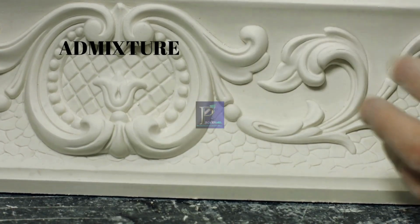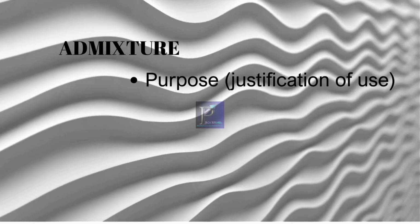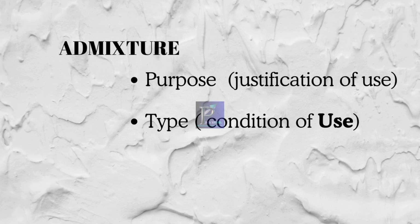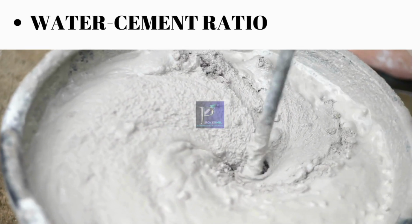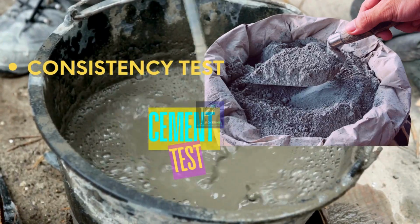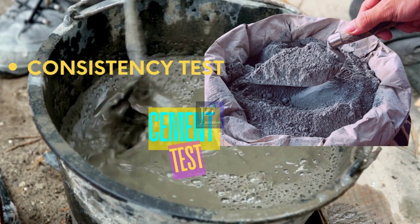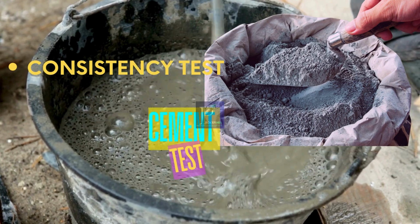The next consideration as per the standard is on admixture. Two factors to be considered here are the purpose of admixture like plasticizer, air entrainer, etc., and the type of admixture along with their conditions. The third one is maximum water cement ratio. Cement consistency test, which determines how much water is needed to create a consistent cement paste based on the weight of the cement, water quantity, and the penetration index.